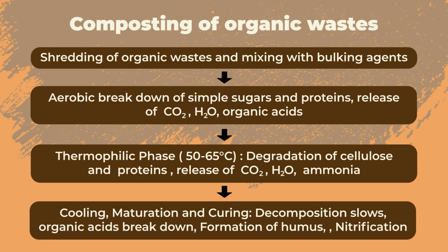In the final stage, the cooling or maturation and curing stage, the decomposition will be slow, the temperature will be lower, and the organic acids will break down to form humus, and there will also be nitrification. The ammonia will be converted into nitrate, and that will enrich the quality of the compost, which can be used as the soil fertilizer.